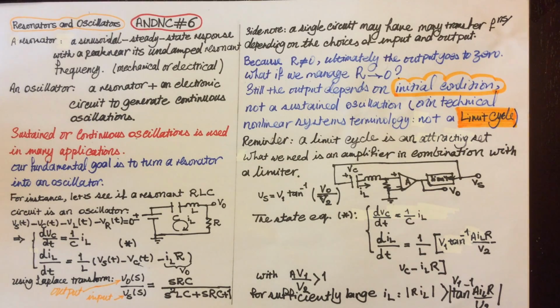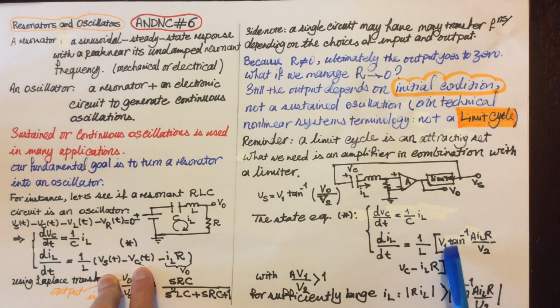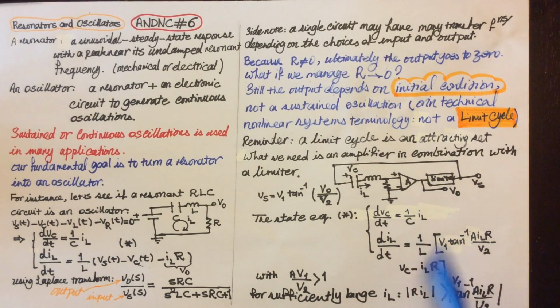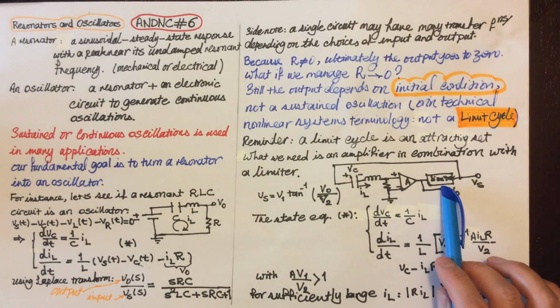To summarize what we did, we talked about this RLC circuit. This is super important in microelectromechanical systems because we can then replace this with a micromechanical resonator which has a feedback loop for sustained oscillation. So the second term, the V_S, is now replaced with this feedback. This feedback has a limiter essentially, so it cannot become extremely large. It starts growing with this I_L, but at some point it saturates.